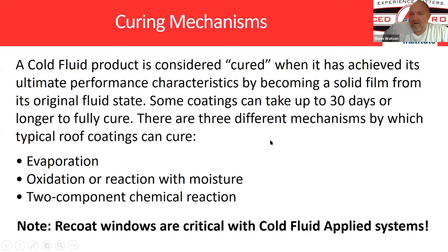If you're going into the rainy season and you're going to try to put down a coating, do you think you want something that's going to take 24 to 48 hours to cure, or do you want something that's going to cure quicker? Those are the kind of things you need to pay attention to. Sometimes the faster cure windows tend to be on the chemical reaction side versus evaporation. But along with that comes additional costs.